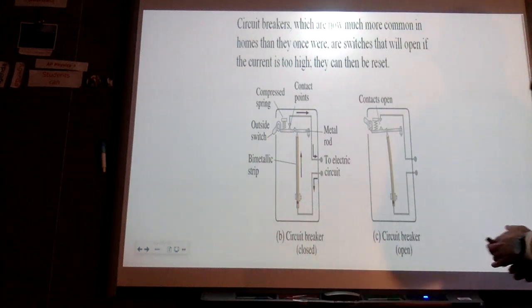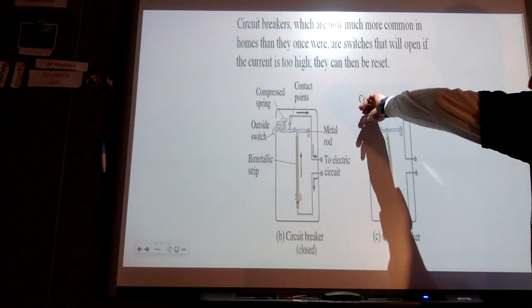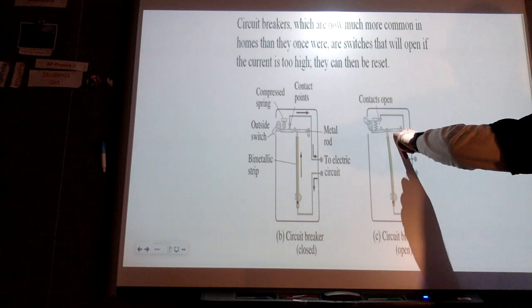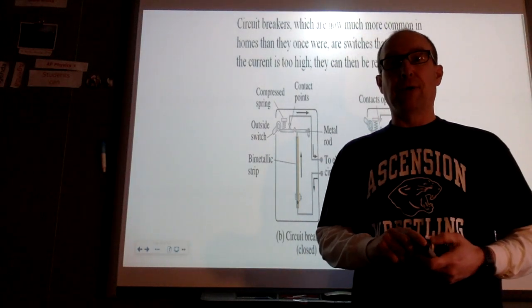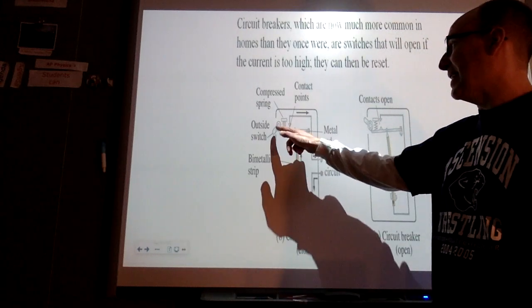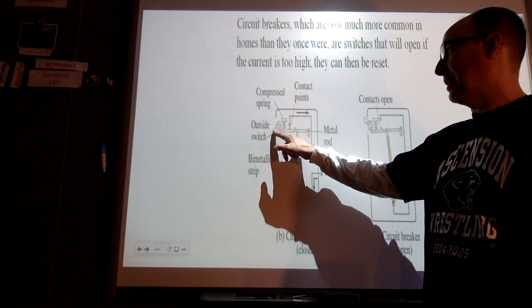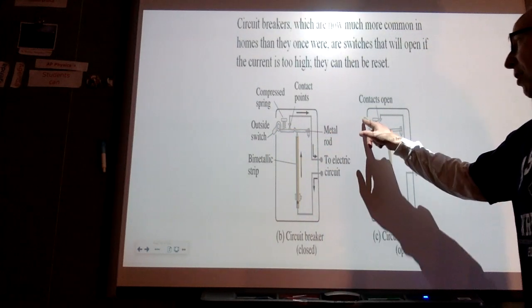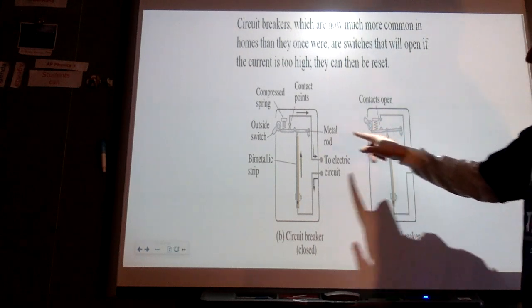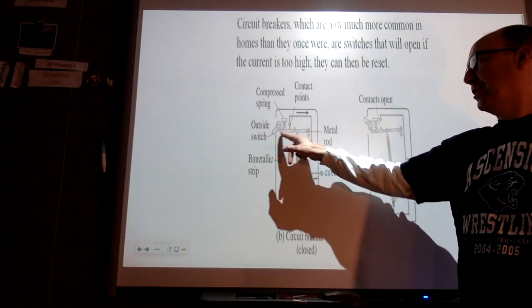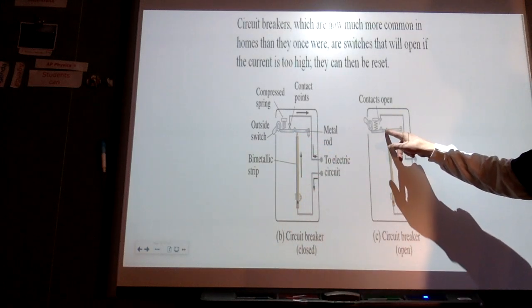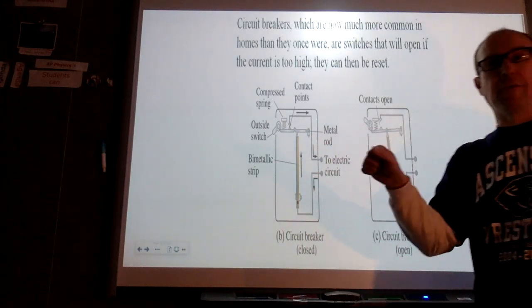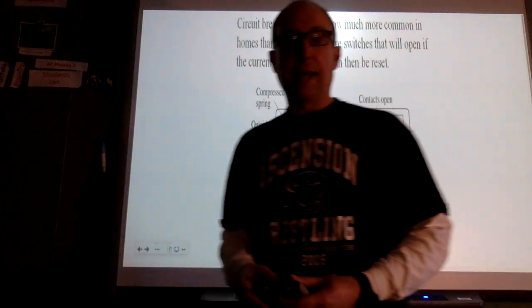And then all you have to do is forcibly reset this. If you've ever turned on or off power in a circuit box, it's easy to turn it off if it's not flipped. It's harder to flip it back on. The reason is when it's not flipped, you're just sliding it across into that little groove. When it is flipped, you're trying to get it out of the groove. So you have to be very forceful to do that.